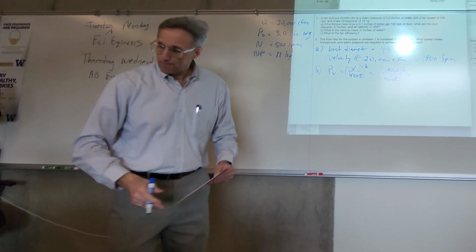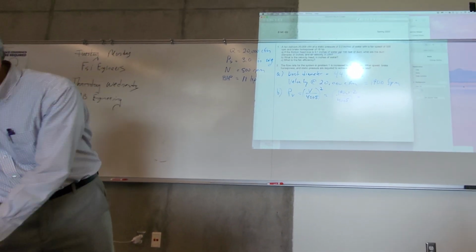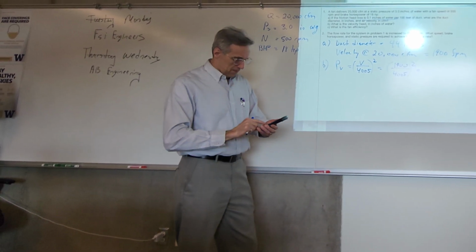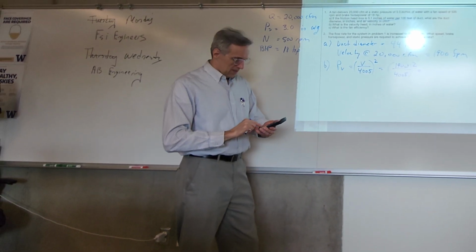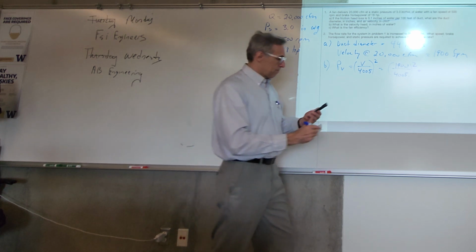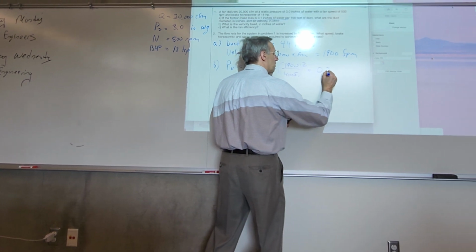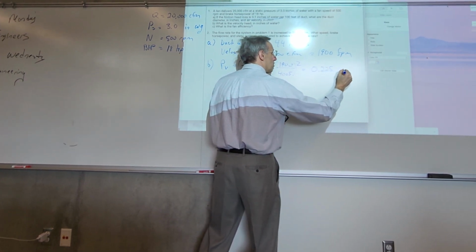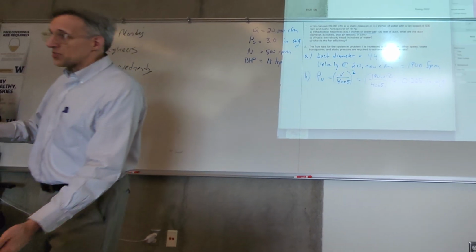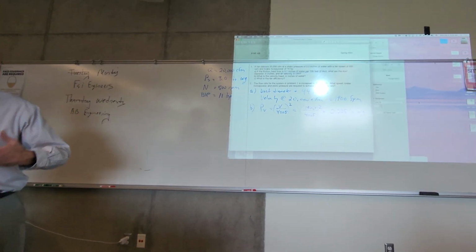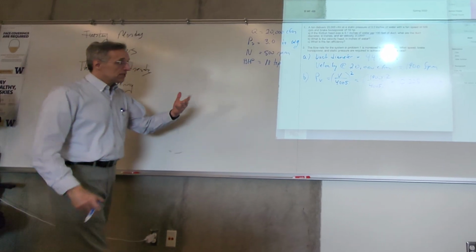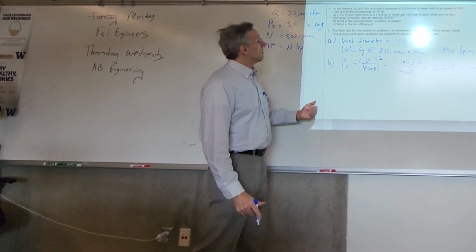And we get 0.22 maybe? Yeah, 0.225. On these larger systems where you start to build up static pressure, the velocity head becomes insignificant, and sometimes it's ignored in a big system like this. It's just not a lot.